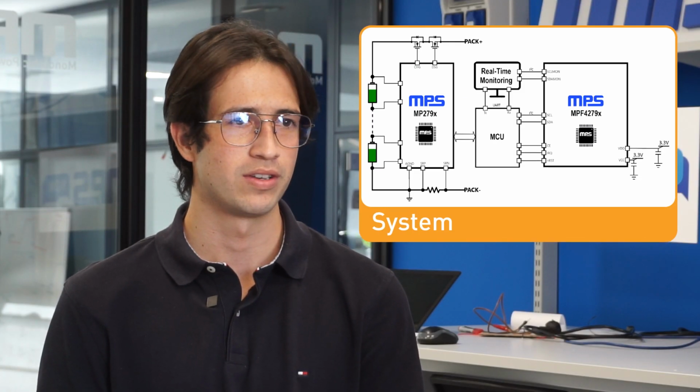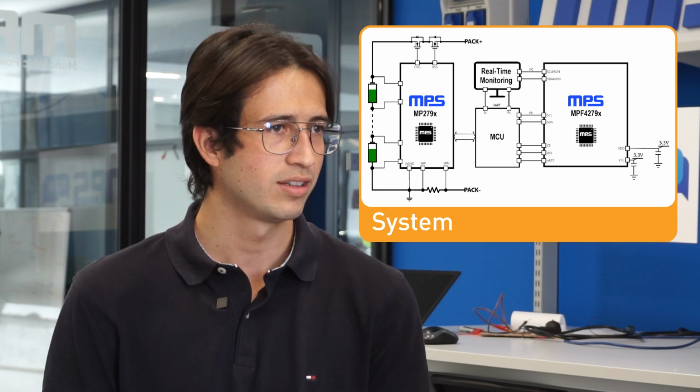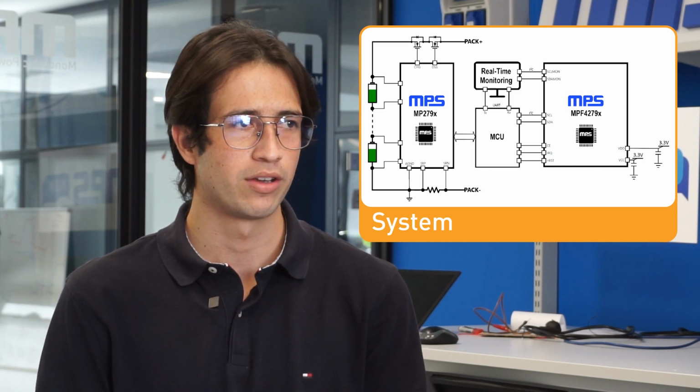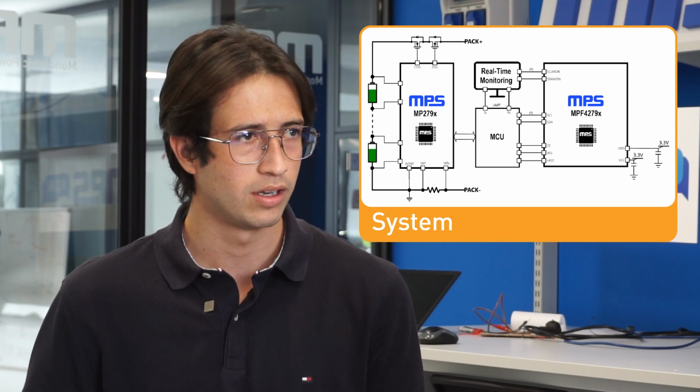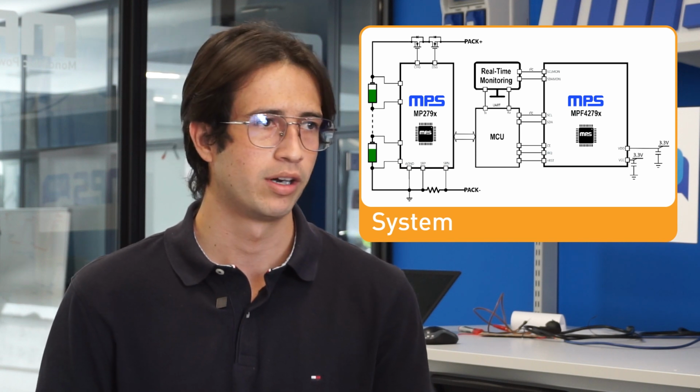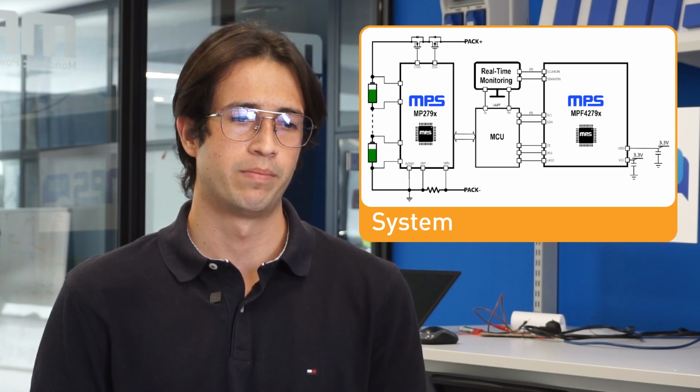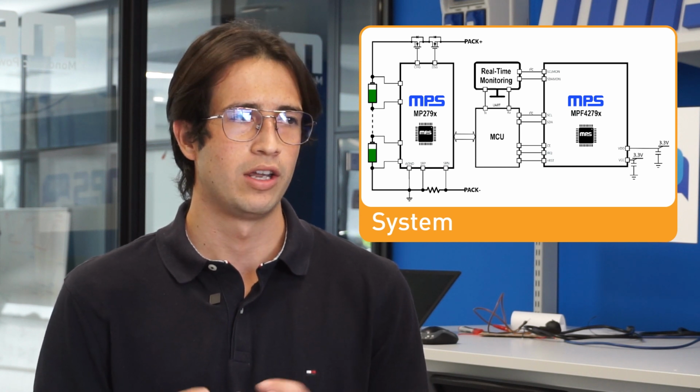All right, great. How about we start with just the top-level battery management system, a BMS, and then we can get into how fuel gauges are part of that system. Yeah, sure. First of all, the battery management system consists of basically three ICs, we would say. Battery monitor and protector, the main MCU, which shares information with the other systems in the e-bike, motorbike, whatever. And then we have the fuel gauge.